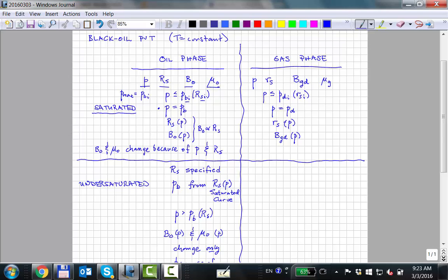The total GOR is the composition of your mixture in a black oil formulation, because the total GOR gives you the total amount of surface gas divided by the total amount of surface oil. That's a ratio. But given the ratio, you can actually calculate the fractions, mass and mole, if you wanted to. So the total gas oil ratio in that Lego piece tells you the composition of the system.